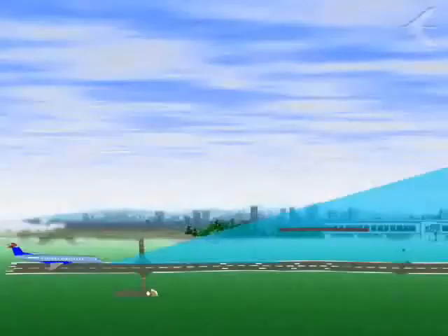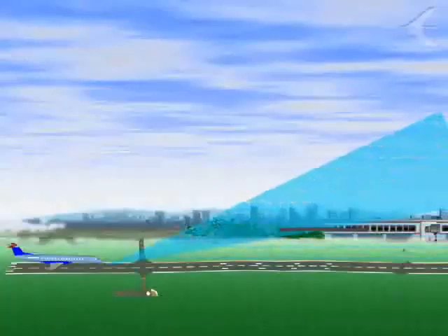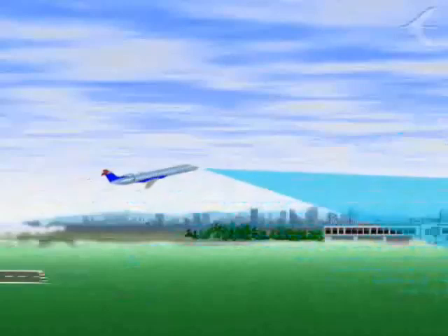Takeoff and landing. On-ground operations require upward tilt to avoid ground returns. Initially, a 15-degree setting will paint convective activity at 15,000 feet and 10 miles range. If a tilt setting below 4 degrees is used for takeoff, some ground returns will be detected until passing 5,000 feet AGL.